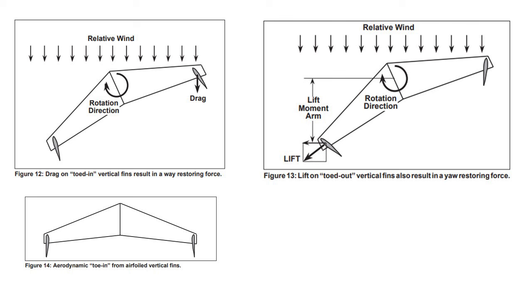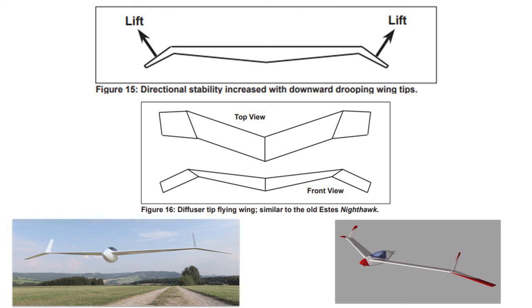As a quick sidestep from the winglet geometric properties that we are reviewing right now, there's a cool little trick with wingtip sections where we can obtain directional stability on a swept wing through negative dihedral, which is anhedral, and twist. Simply put, the wingtip is bent downwards and at the same time tilted forwards. Now this definitely doesn't have to be across the whole span, and we should really be careful not to induce rolling instability with any anhedral. If you have any questions on what affects yawing and rolling stability, see my last video about aerodynamic stability.